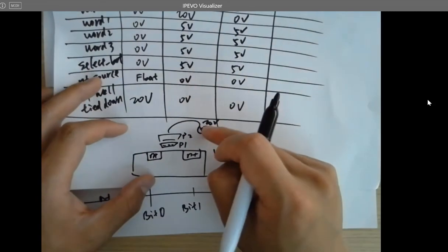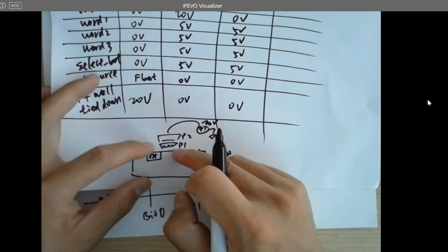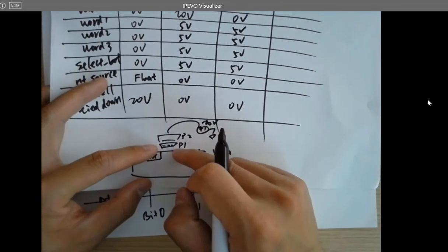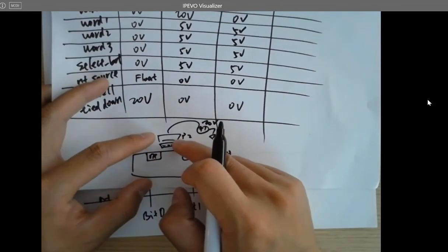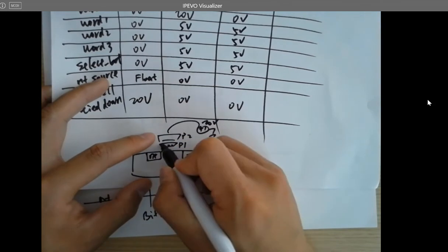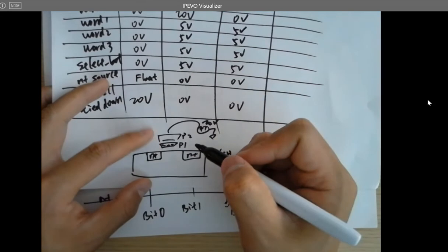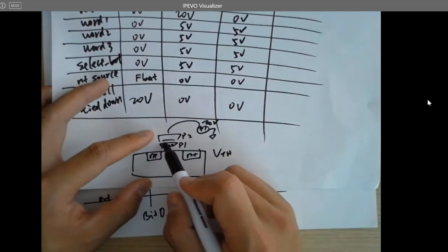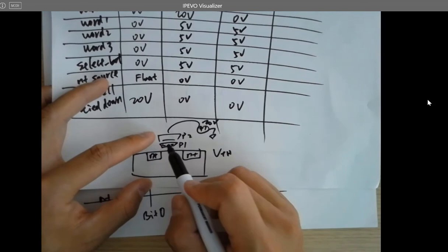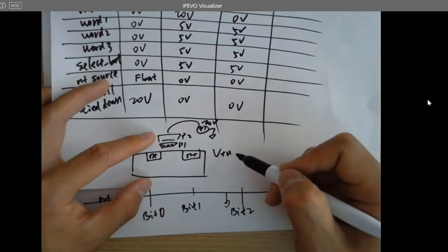The gate voltage is not directly shorted to P1 as usual. It's being shorted to P2. So there's an intermediate layer in the middle, which is a floating gate, which traps all the charges, electrons inside. So whenever it's being programmed, you got electrons in the middle. And are the electrons increasing the VTH or decreasing the VTH?